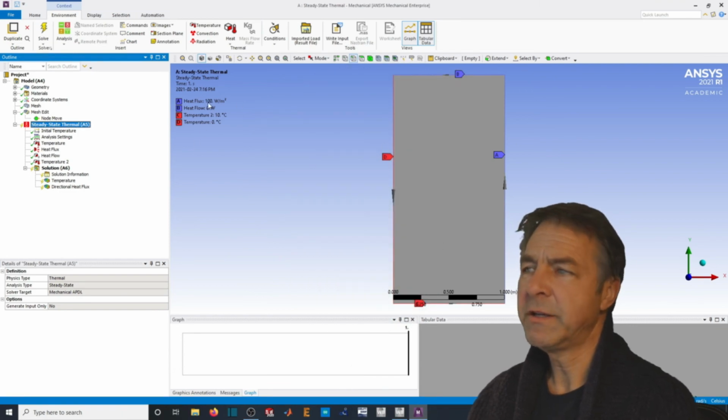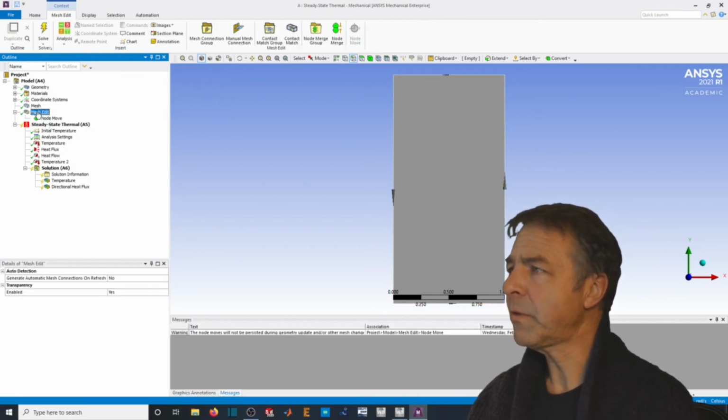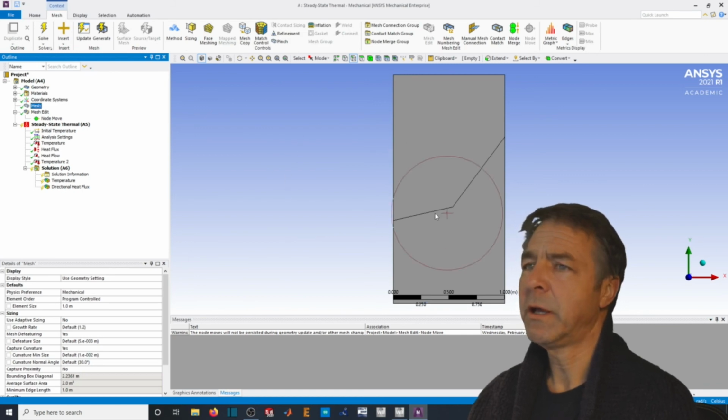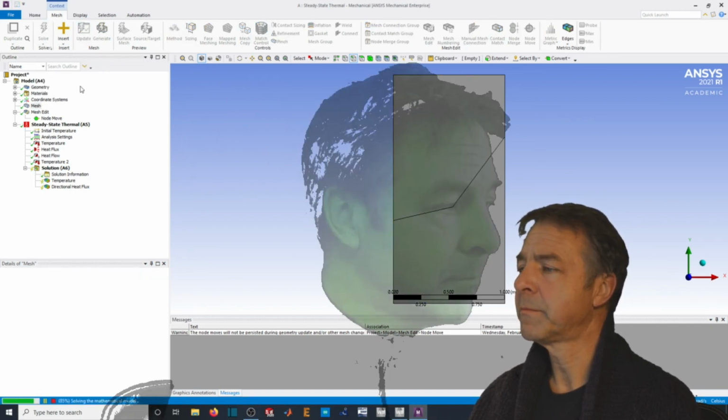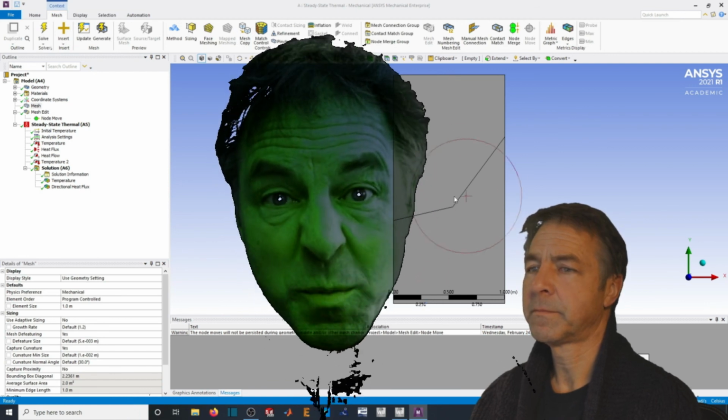So now you can see I've got my boundary conditions showing up here in, if you click solid state thermal, I've got a heat flux of 100 watts per meter squared at A. I've got a heat flow that's insulated of 0 watts at B. I've got a temperature at C of 10 degrees C and a temperature at D of 0. And if we look at my mesh, I've got this wonky mesh that I created. So let's try solving. It's going to be made of aluminum.